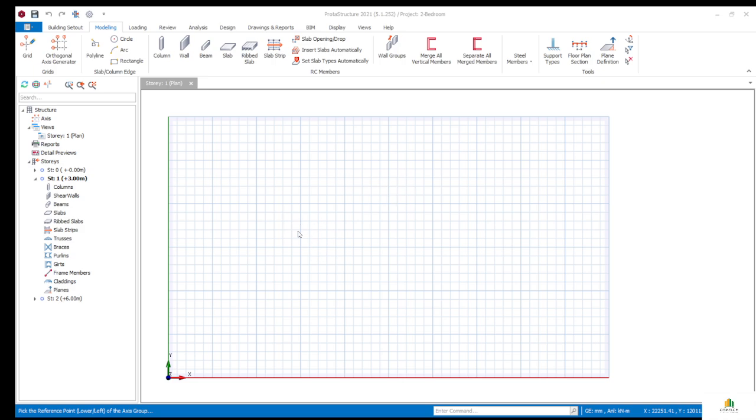Then we have direction 2 axis. The direction 2 axis are the grid lines that move vertical like this, and the axis label is 1 and the step is 1. That means in that order, 1, 2, 3. Then the axis spacing 2, the spaces between the grid lines, has 5,000 asterisk 3, right? So let's delete it. Let's delete the other direction 1 axis, that 5,000 asterisk 1.